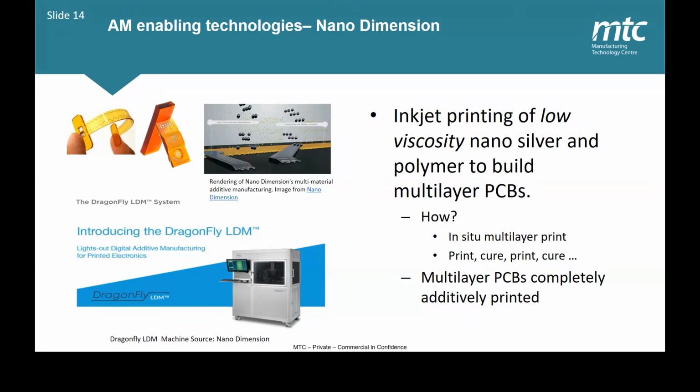Once you calibrate the machine, the process is that it prints the bottom solder mask and pads, then prints and sinters the conductive layer on the fly. The next process, it prints and polymerizes the dielectric layer, and this process repeats for each layer, and finally finishes printing the top solder masks and pads.